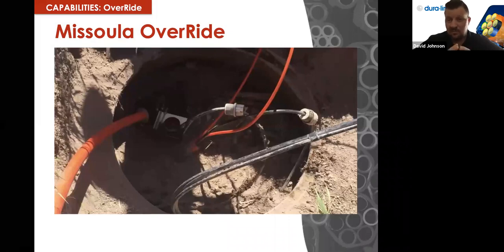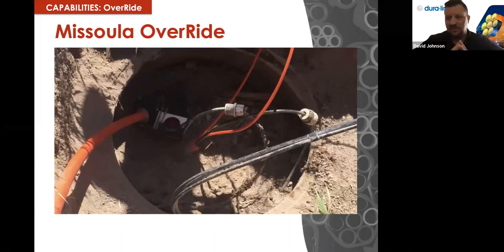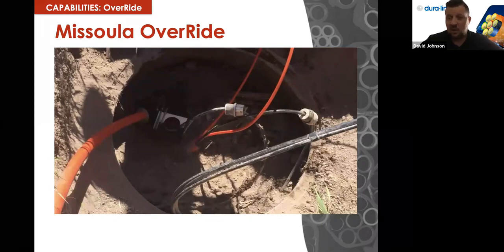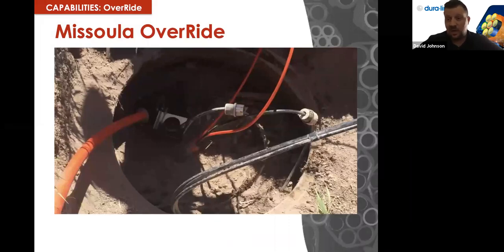The points are 90 to 110 PSI. You'll hear the air go through the whole reel. Once you stop hearing that air, at that point, it's full. Then you're going to turn off the air and uncouple that valve. The valve will stay on the reel to hold the air in. Then you wait about five minutes and make sure that air pressure is still holding between 90 and 100 PSI. So that's how you use it. It's all tools. It's getting those tools from GMP and making sure that we have the right setup.